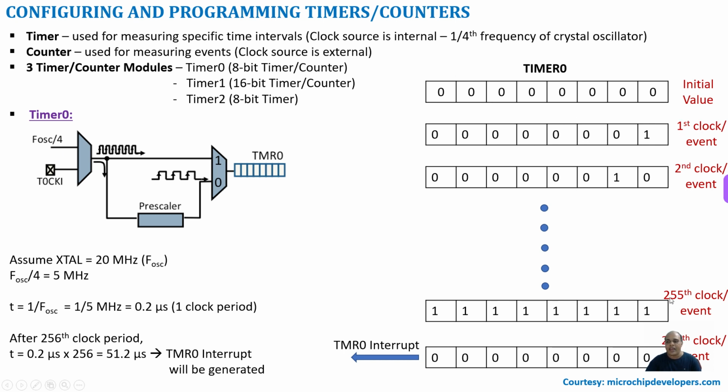So this frequency can be altered by putting different values in the prescaler register. Instead of 2, I can put 4, 8, 16, 32. So depending upon that value, this clock frequency will get modified. Thereby the incrementation frequency also is going to change. If the incrementation frequency is changing, automatically the time of incrementation is also going to get varied.